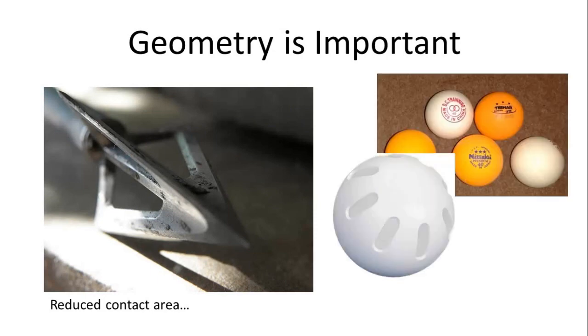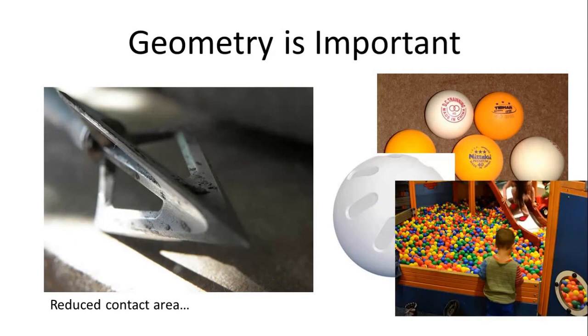Conversely, hollowing out the ball into a spherical shell reduces both the mass of the projectile and changes how strain is distributed. This would be like a table tennis ball, or a wiffle ball, or those hollow plastic ball pit balls in play places. You know, for kids. A solid ball of the same plastic would not be as bouncy. There are a bunch of other geometric and structural variables like angle of incidence, panel thickness, porosity, internal or external reinforcement, yada yada yada, you get the picture.